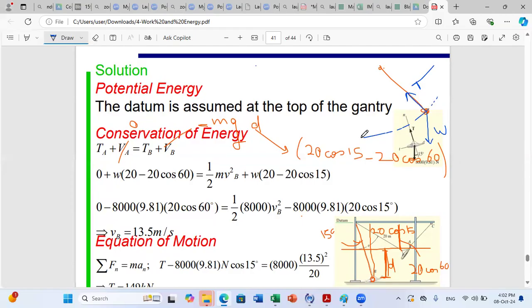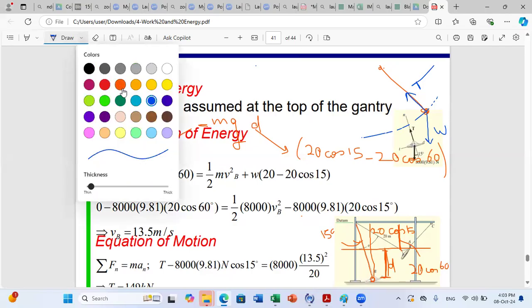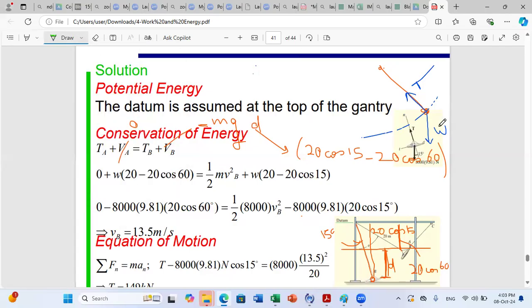So in general, whenever I have circular motion, one of the easiest frames to work with is the UN UT frame. I can now draw on my figure the UN UT frame. UT is tangent to the path. UN is along the normal direction. Since I am interested in finding the maximum tension, I need an expression for this tension.